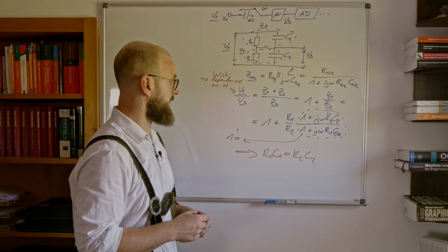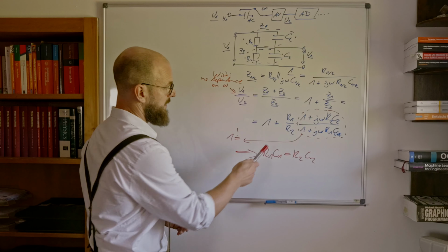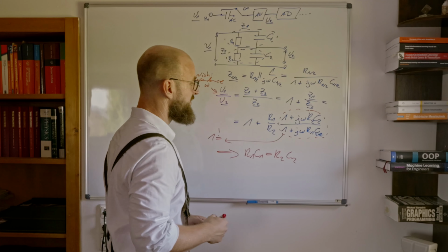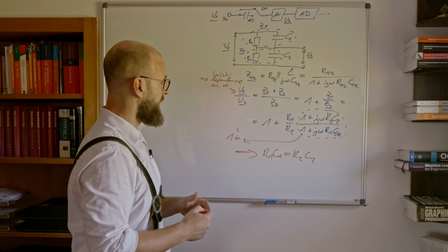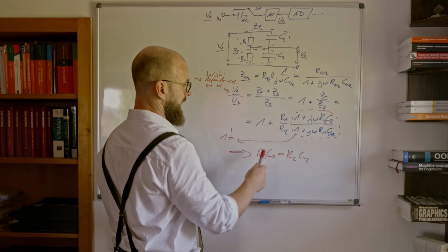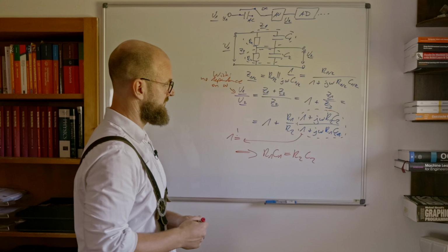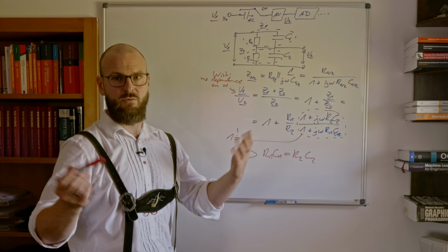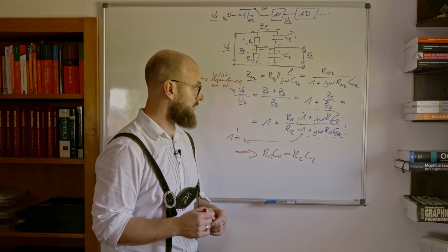Still, we can define our ratio because, for example, we can choose R1 and R2 beforehand. Meaning, if we want to split the voltage in a ratio of 10, we choose R1 to be 9 times larger than R2. Okay, R1 and R2 are fixed now, for example, with 1 mega ohm and 9 mega ohm.